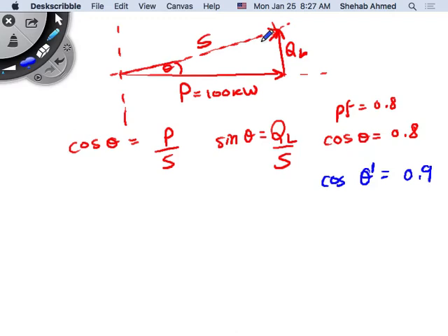It's like the analogy for the bicycles, right? Somebody on the bicycle now leans on the other side so that the bicycle doesn't fall down. So now I want to improve my power factor, and I can draw a line here. Obviously this angle will be smaller. What's inverse cosine 0.9? 18.19. So it's almost half of the original angle. So I can draw my theta prime line here.